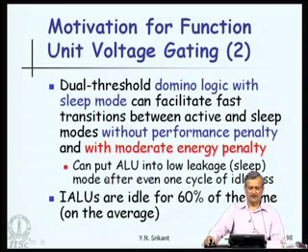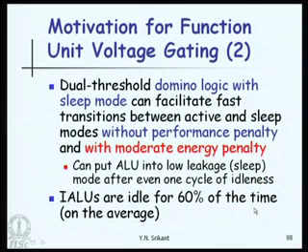Now, the problem is if the switch requires a fair amount of energy, then is it useful to put the CPU in sleep mode very frequently? Obviously not. So, the one cycle of idleness is all that we require to put it into low leakage mode, and we also know the factor that motivates us is integer ALUs are known to be idle for 60% of the time on the average. That is, the integer ALUs do very little for 60% of the time in general.